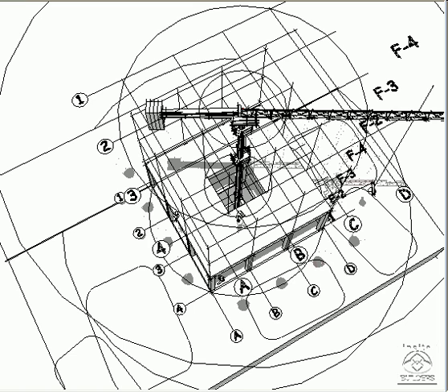Crane operators must be aware of these distances because of load limitations, and the control zones restrict operation of the crane, limiting its movement. For example, swinging a steel member across the zone would be dangerous for the management structures that are in this area: the job trailer, vehicles, other storage. On large projects, the laydown areas will also have grids. These designate the location of materials waiting for installation.